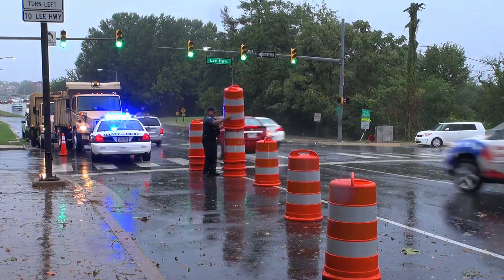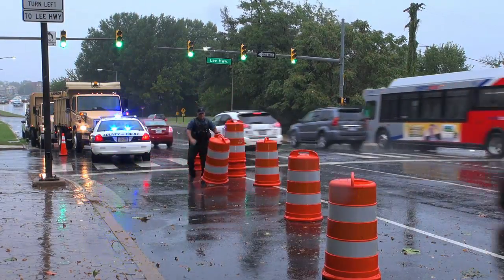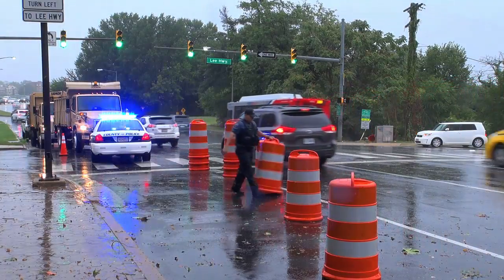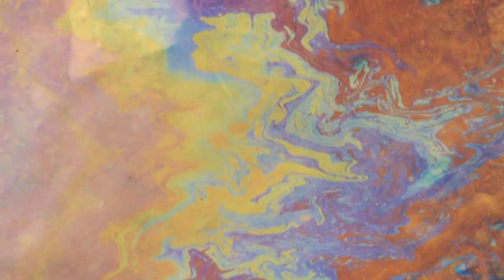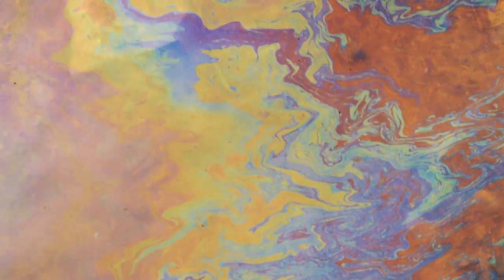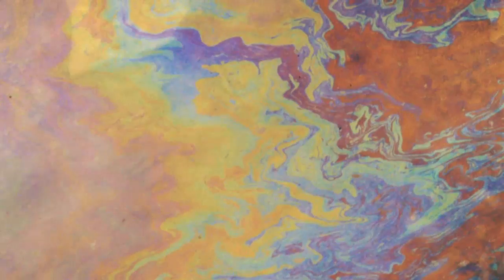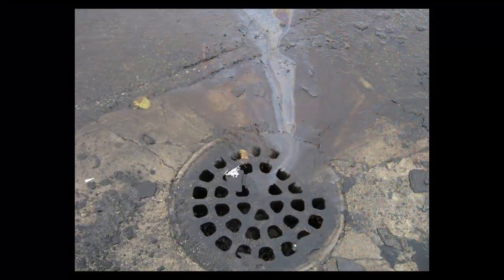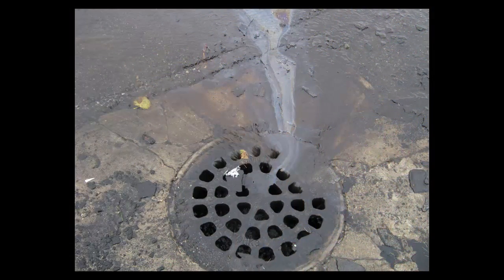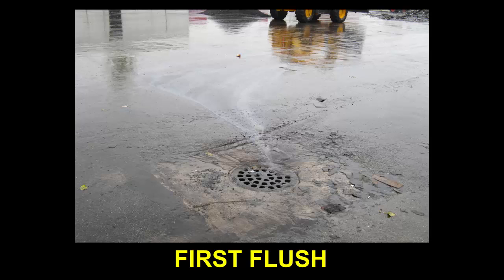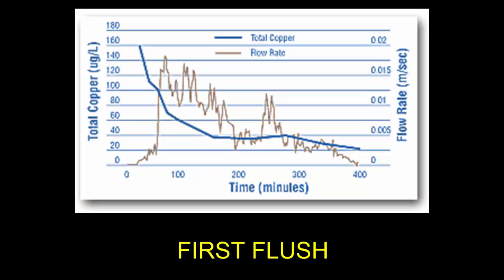Most automobile drivers are aware that roads are slickest after the first few minutes of a rainstorm. It is in those first few minutes that oil, grease, and other pollutants that have accumulated on the pavement are picked up by water and transported to the storm sewers or roadside ditches. This washing action by the stormwater is referred to as the first flush. It has been determined that this first flush of stormwater runoff contains the highest percentage of pollutants.